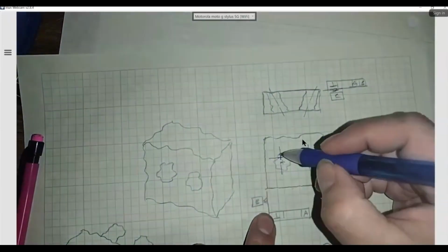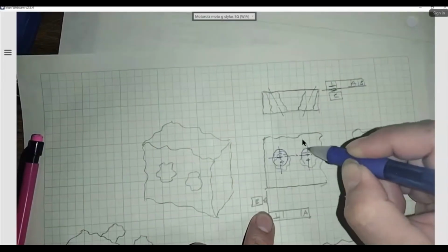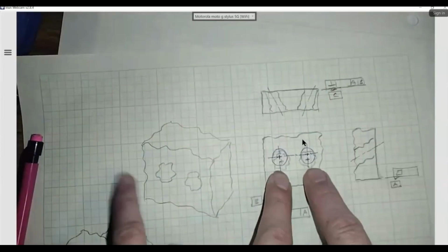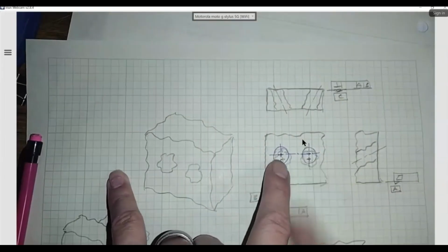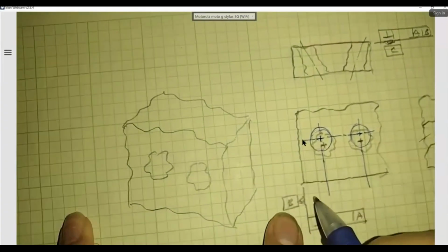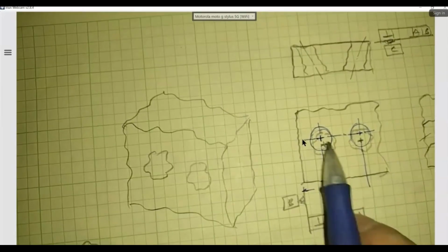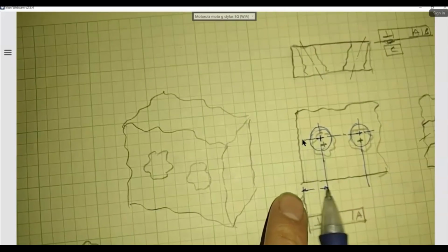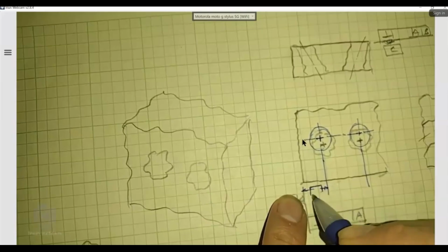Let's say that my perfect hole is here, like in my model. Right? So my model is perfect. 0.0000 till infinity. The real one is the one below. You guys see it? Well, I need to ensure where my bullseye is at, which is the perfect condition, so I need to dimension it from my datum. So I'm going to go over here, and I'm going to dimension it from my datum. Okay. I'm calling out the perfect position. So my perfect position cannot have a plus and minus. And the way I tell it that I don't want to have plus and minus, I put a little rectangle.